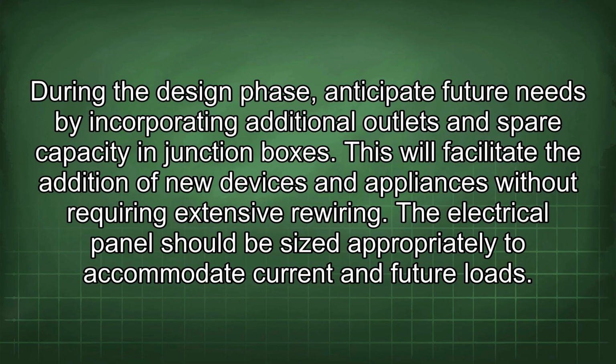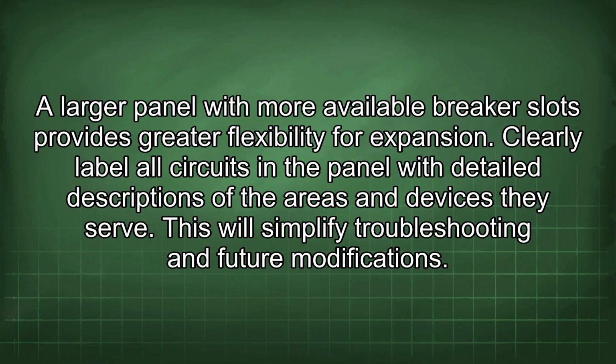During the design phase, anticipate future needs by incorporating additional outlets and spare capacity in junction boxes. This will facilitate the addition of new devices and appliances without requiring extensive rewiring. The electrical panel should be sized appropriately to accommodate current and future loads. A larger panel with more available breaker slots provides greater flexibility for expansion.